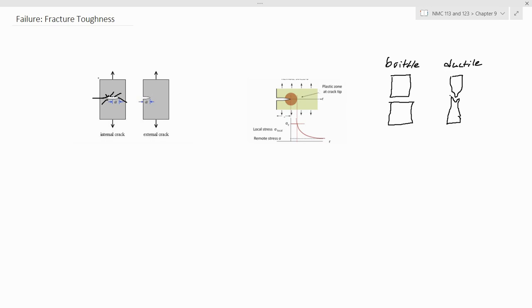So even though the force of the pricking on your hand is the same, the wound is an area that has a high concentration of stress raisers. The same way with the material, with these cracks, there's a higher concentration of localized stress where you have a crack.